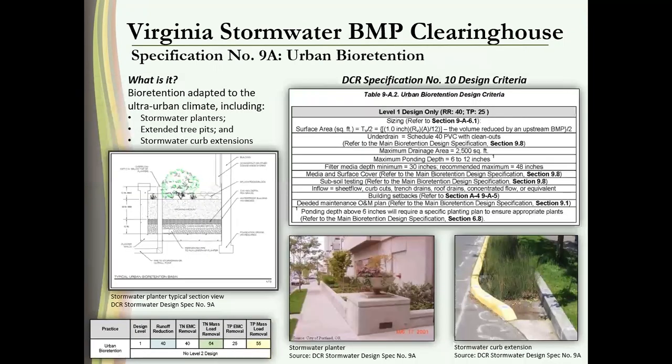There are, as I mentioned, different kinds of bioretention facilities. One that we're seeing more and more frequently is urban bioretention. Urban bioretention just means that it's kind of small, in a limited area, usually with impervious surfaces around it, like concrete for either the sidewalk or the building, and it's going to have things like liners. So there's a little bit more in terms of design, but again, you get a nice little green spot in front of your building.